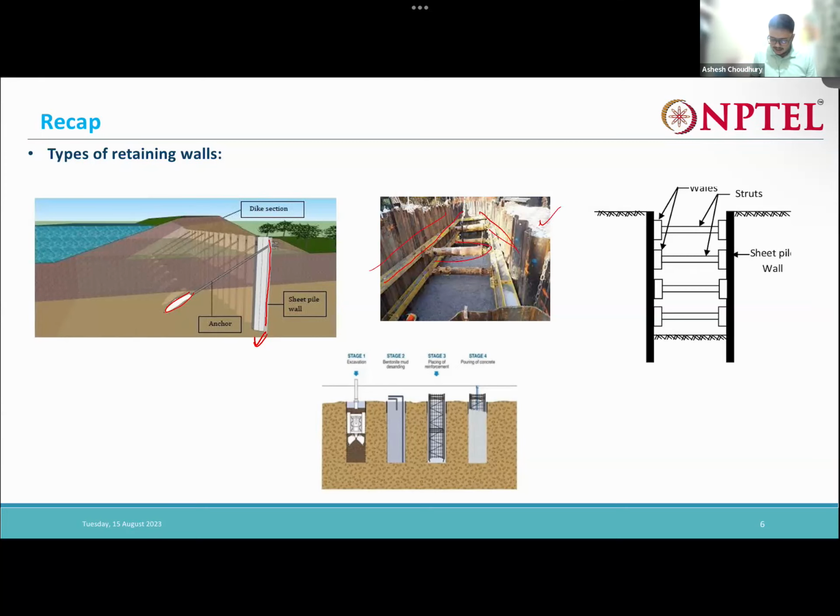The first image you see is of the general type of reinforced soil retaining walls that we use. You can see here we have the concrete foundation or base, this leveling pad. Now on the leveling pad, you see these modular blocks, right?